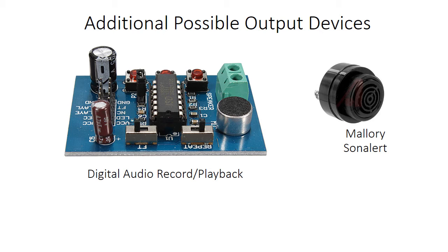It'll record up to 8 to 10 seconds of audio, and then run that into my aux input on my communications transceiver. Usually there's an intercom feature on most of the modern ones. That way it would come through your headset. You'd need to do a little work to tailor this to make it actually function. You'd need a 5-volt regulator and a couple resistors probably, nothing fancy.